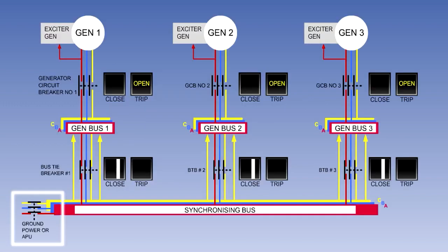It can be used, amongst other things, to drive 1 or 2 AC generators for ground operations prior to engine start, or, in some aircraft, for emergency electrical supplies in the air. Because the APU runs at a constant speed, its generator does not need to be driven through a constant speed drive unit. The APU generator cannot normally be paralleled with the engine-driven generators, and can be only connected to the bus bars when no other source is feeding them.